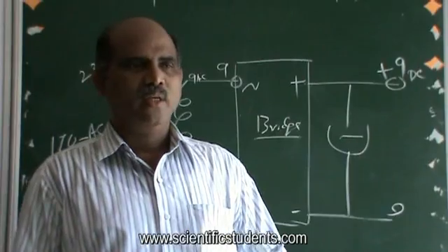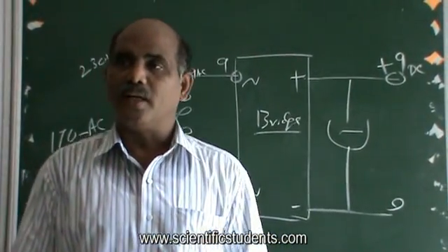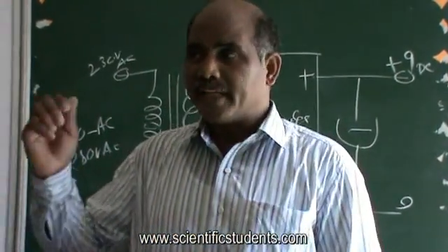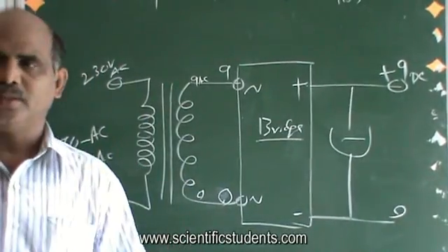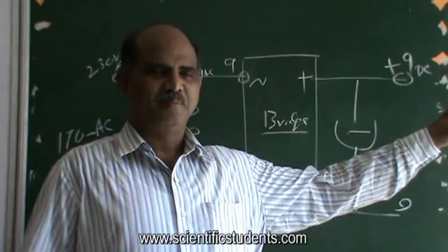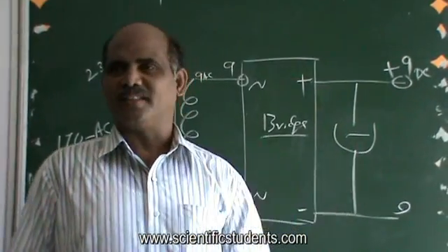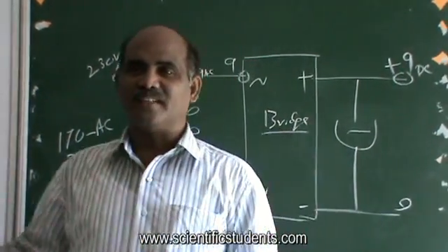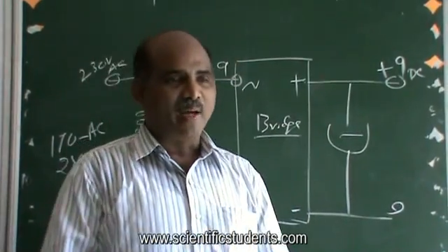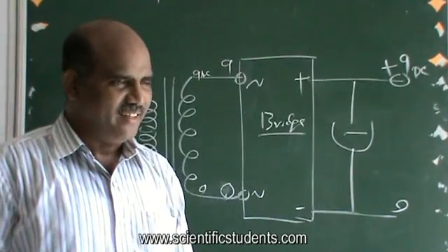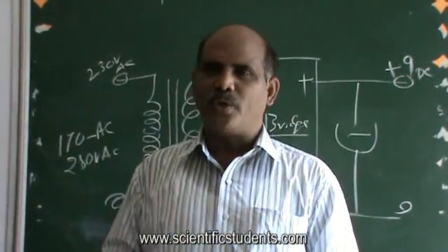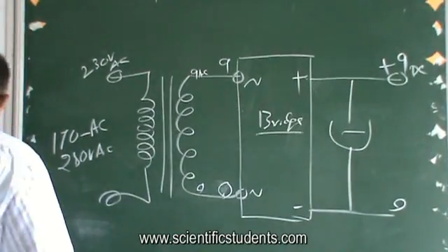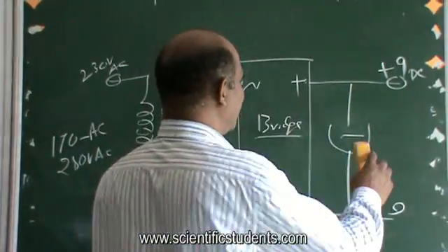That is called RPS, regulated power supplies. So what happens in regulated power supplies? Irrespective of your input voltage variations, the output is kept constant. The output is maintained constant irrespective of input voltage variations. How nice is that? So how does it work? Interesting? I will show you one example here. After that you can learn many more. As I present to you, my batch, I wanted to give one very simple example.